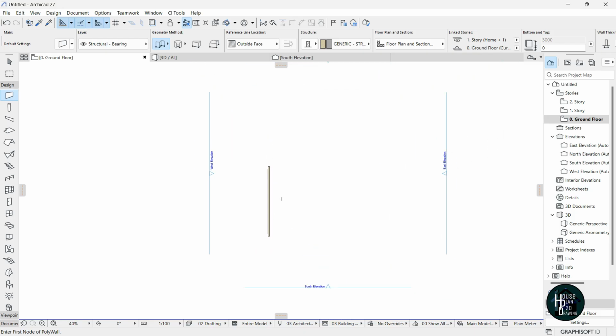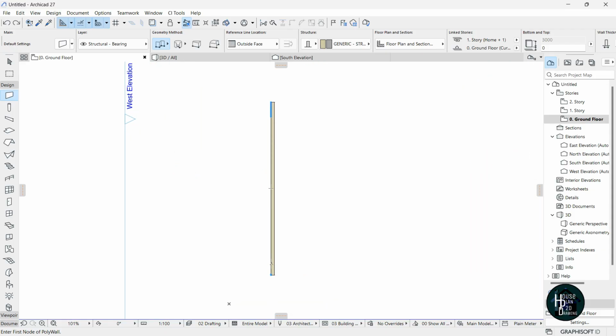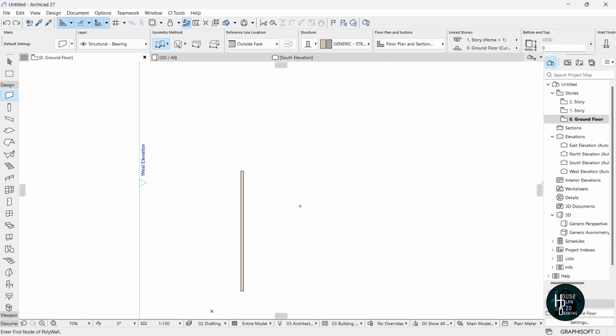What I just did right now can be done in different ways. I'm going to be showing you something that I always show in all of my videos, so there's always a clear understanding of how to go about them. For instance, when you want to draw your line, your wall, you click, you click, you click. If it's not giving you this chained type of drawing, I want you to just hold this down and select this icon right here. So you're going to be able to do your chain in Archicad.